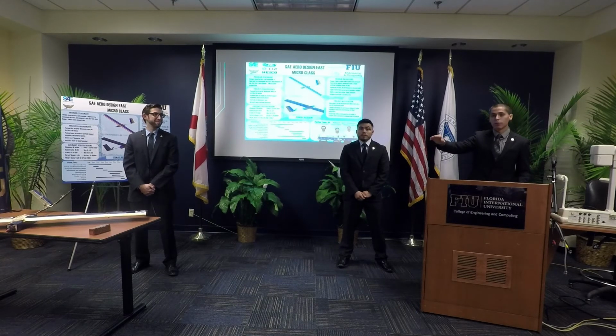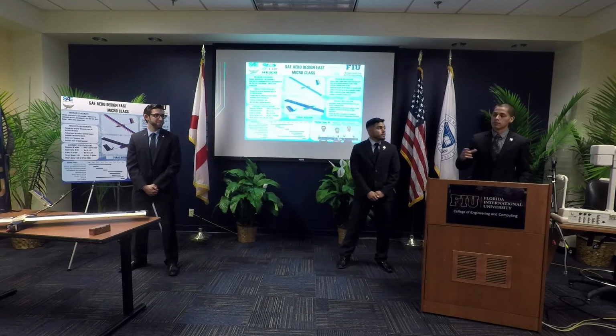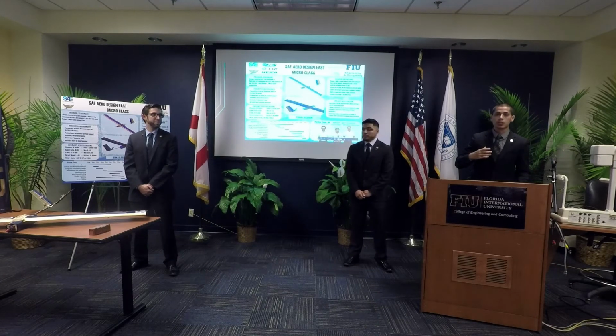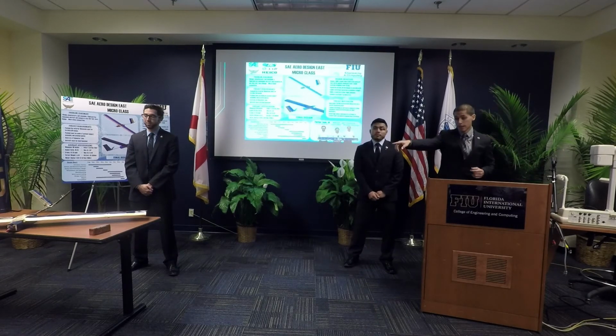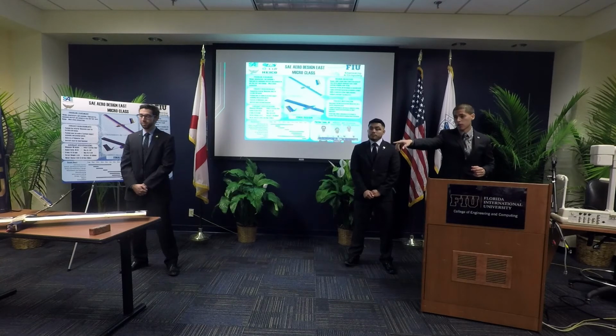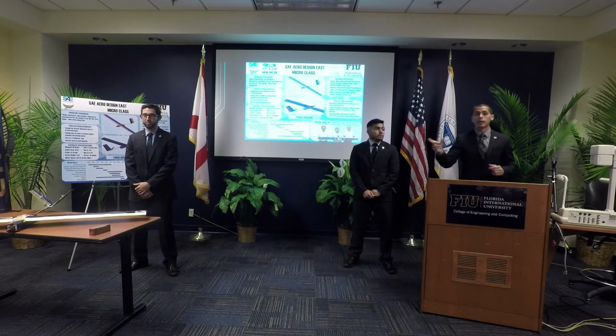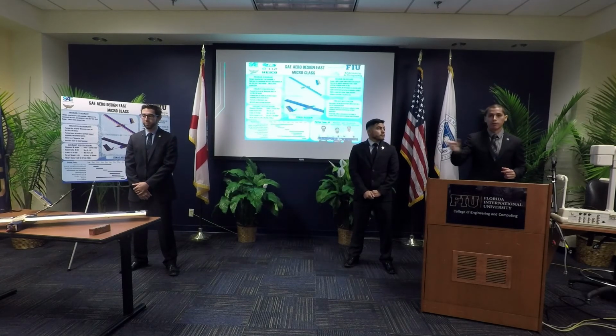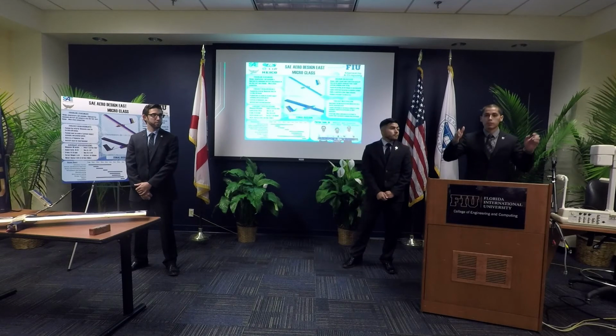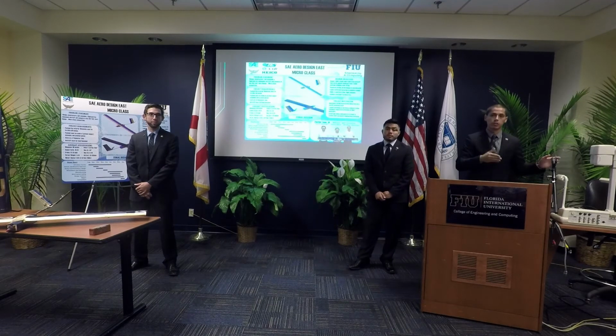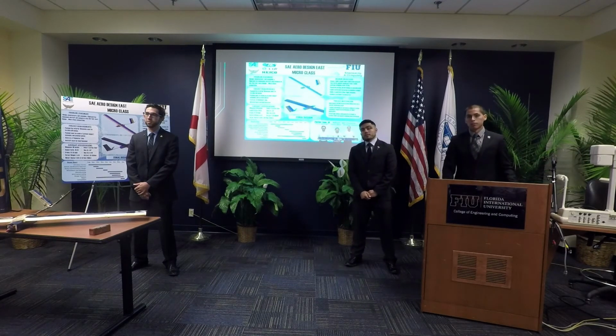We have slots for the flying wing there, and that needs a different CG. So the actual payload layer, which is that copper rectangle there, can be moved inside the fuselage fore or aft depending on where you want to set it up. So in a sense, the counterbalance is already built in. All we've got to do is wedge it one way or the other.